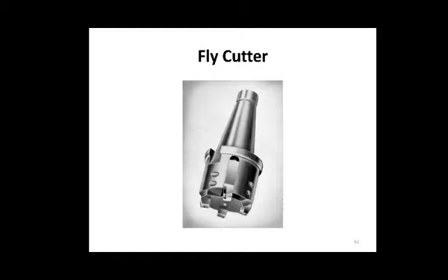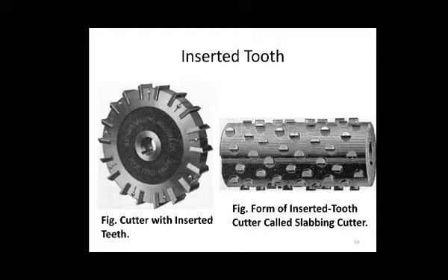End mill has cutting teeth on the end as well as the periphery, and it is fitted to the spindle by a suitable adapter. End mills have two types. Solid end mill has shank and cutter integral, usually smaller, with either straight or helical flutes, and has two flutes or four flutes. The second type is the shell end mill with a separate shank.